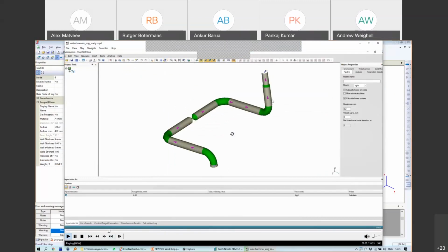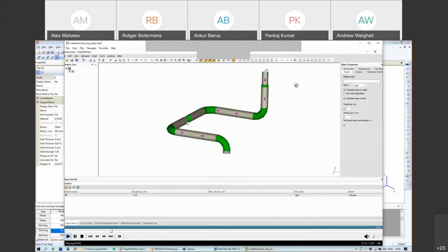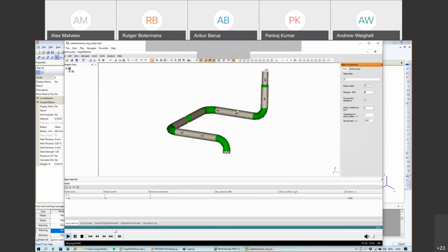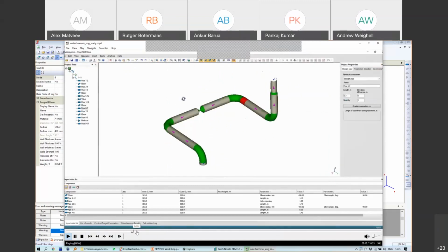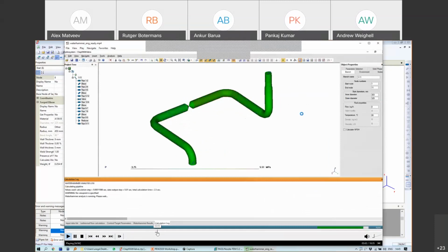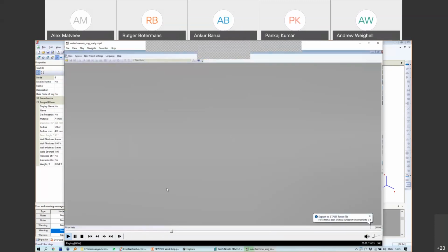It can calculate the water hammer loads automatically. For example, this valve is closed very quickly, and this causes the water hammer effect in this piping system. So the Hydro System software can calculate the surge effect of water hammer, and it will calculate the load values.